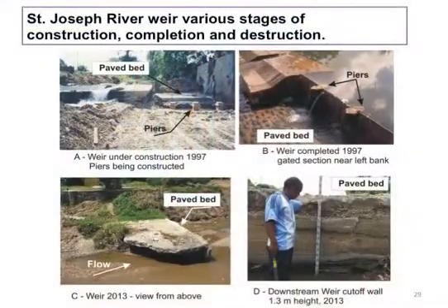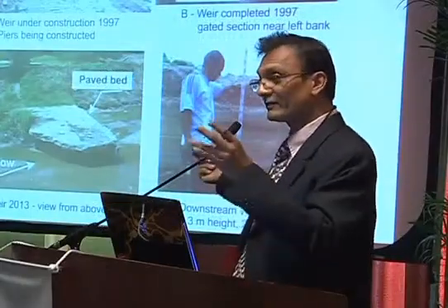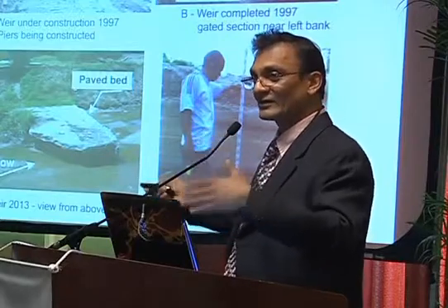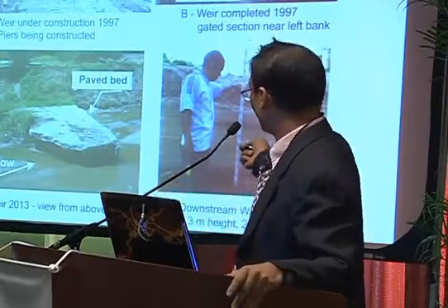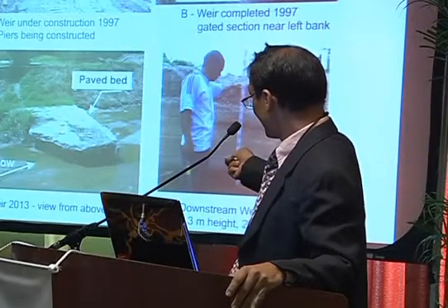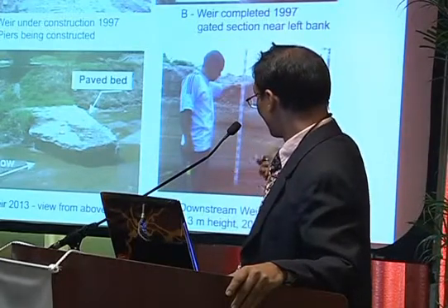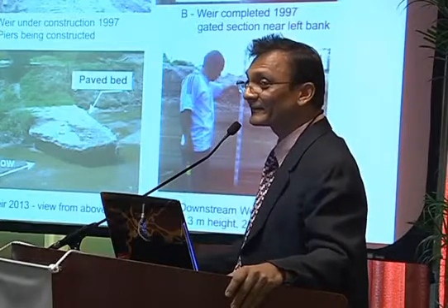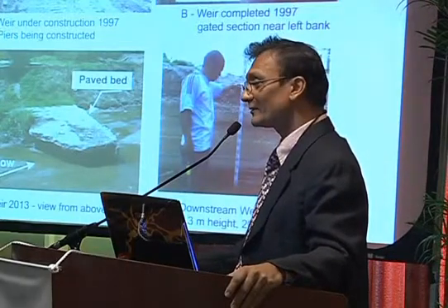Now this is the old days where you took a picture and you went and you printed, right? So, construction work, the broad section, and this work was done by Drainage Division workers. So the concrete paving there, this is the finished product. These are slabs of stones to dissipate the energy so you don't cause erosion downstream of the weir. This rough surface is now 1.3 meters above the riverbed. So this could have been avoided.